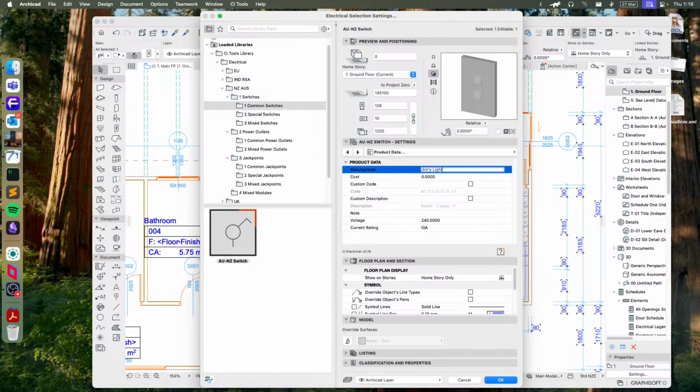So we can easily get to something sensible, and then we can come over onto a different edge. We can adjust the length of this one to make it a little bit longer, and then we can grab the middle hotspot and drop it down. So using this, you can see that once you've drawn up the plan view representation of your cable trays going around the areas that it needs to, you can then come into 3D and do the same to make sure that it does the things that it needs to there.